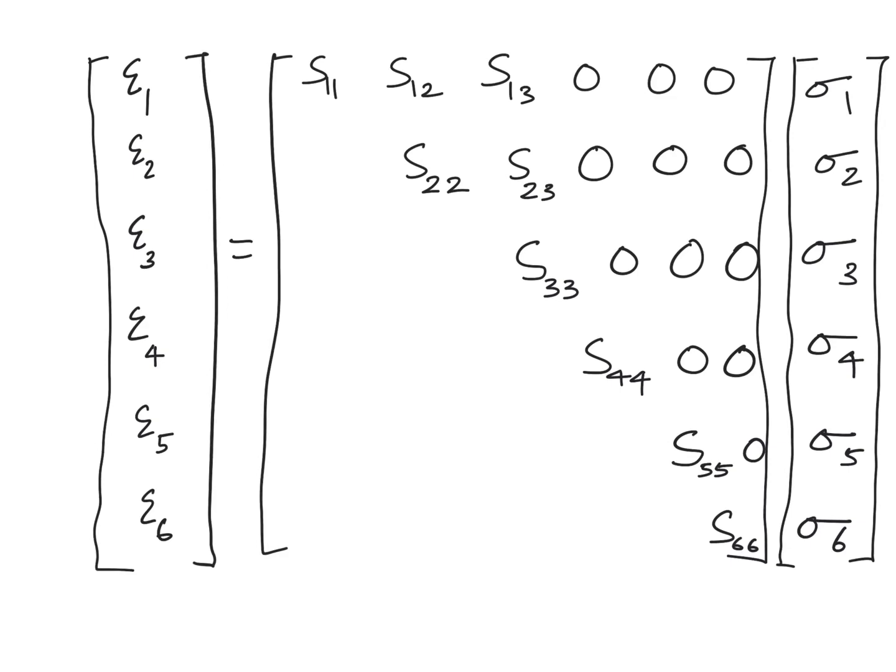because you have strain on the left hand side and stress on the right hand side. That's why it is called the compliance matrix. This can be pretty much remembered like this, because deflection is equal to the applied load divided by the stiffness, where 1 by stiffness is your compliance. So a pretty easy way to remember that. This is analogous to a spring.